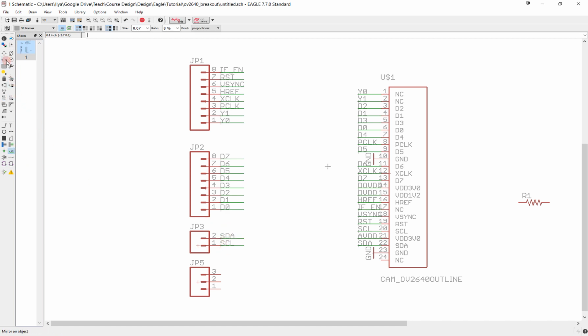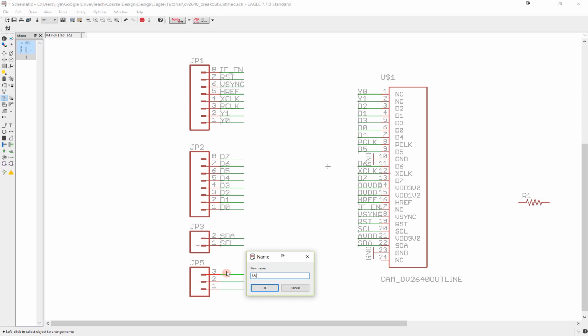And finally, potentially we want to be able to provide our own inputs to the power supplies instead of using the ones that are coming out of the voltage regulator. So I'm going to make a header that's going to allow us to do that. And so here this is going to be one of our power supplies, AVDD, DVDD, and also DOVDD. And once again, let's label those here. And that's pretty much it.